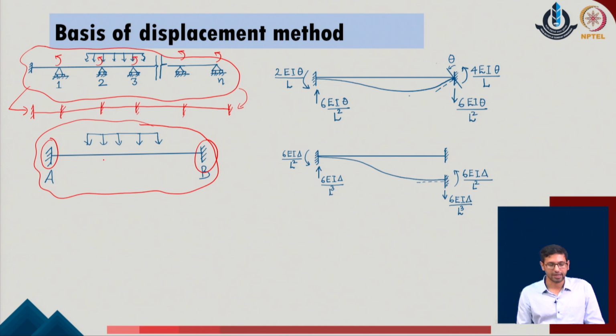The second criterion, as we understand, is that any of the loads which are active on a fixed ended system will typically have the effect only within the span of the given system. Say I come up with a member having some loading on multiple supports, and as a first step I consider my system kinematically determinate by restraining all the degrees of freedom.